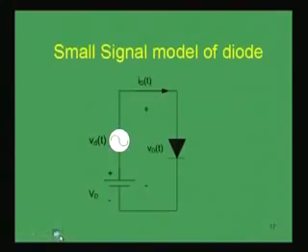But of course, what we are considering is the DC signal, DC constant voltage. But what will happen if we have a small AC signal superimposed on the DC voltage? Then our whole model will have some extra terms, not only the resistance, because whenever this change occurs in the voltage, capacitance effects will come.